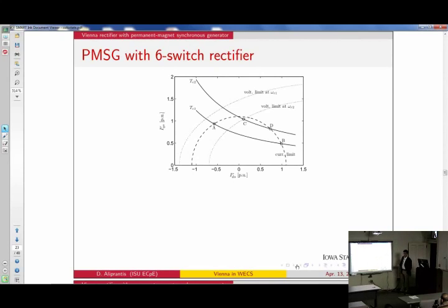So for a wind turbine, what we do is, for any given wind speed, I can find the rotor speed that I want and the torque that I want. So this line here gives me the torque that I want this thing to give me for a given wind speed. And this other line here is the torque for a higher wind speed. So to get this torque, what this plot tells me is that I can use any combination of IQ and ID that are on this line, limited by point A, which is on the current limit, and another point here, B, which is on the other side of the current limit. So I'm limited by current for low wind speeds. For higher wind speeds, because this ellipse shrinks, I'm now limited by C here, which is a voltage limit, and by D on the other side, which is a current limit.